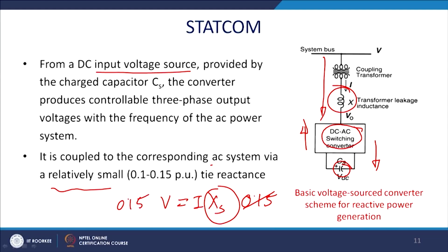So, from there you can calculate the value of XS and thus you can calculate the value of the inductor. Generally the reactance value will be 10% to 15% of the base voltages.